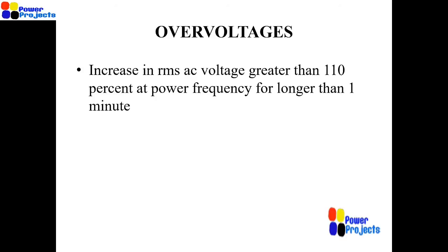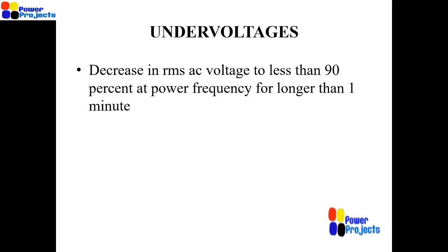Generally, over voltage relays are available to protect against over voltage, or you can have surge suppressors, surge arresters, etc. to prevent these over voltages. Despite that, if your voltage goes beyond, say, 120 percent for 2 seconds, your over voltage relay will be able to isolate your system.